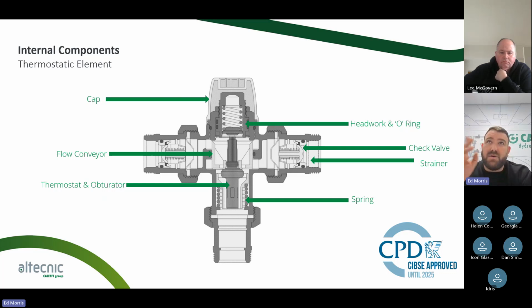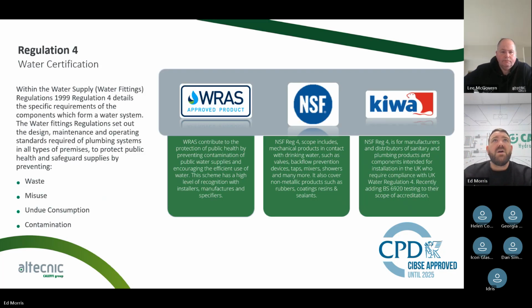As we adjust the top, so underneath the cap is the adjustment knob. As we adjust that knob, what it does, it changes the tension of the top spring, which moves obviously the parameters of the valve itself. So let's say there's no real wizardry that goes on in there. It's very mechanical, but it's very clever the way it works.